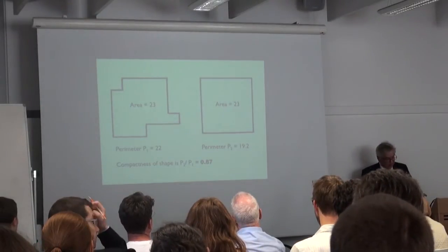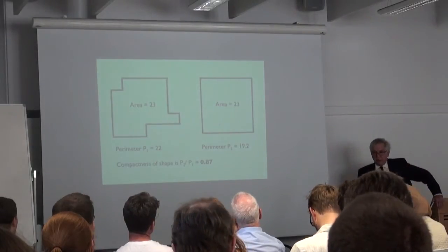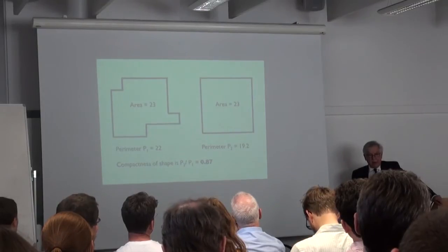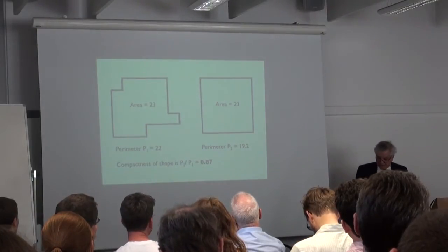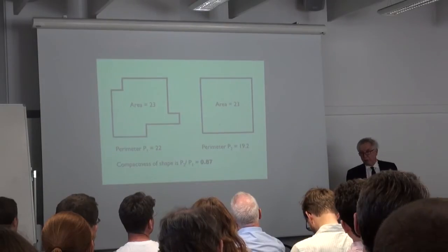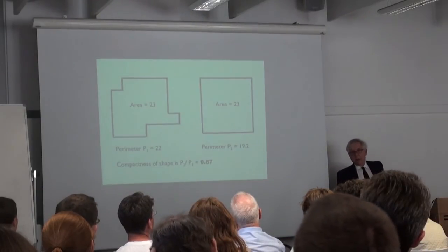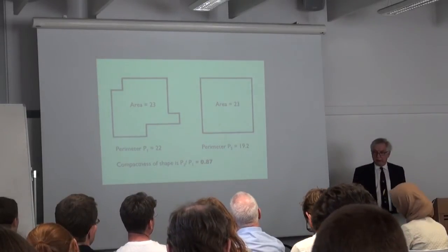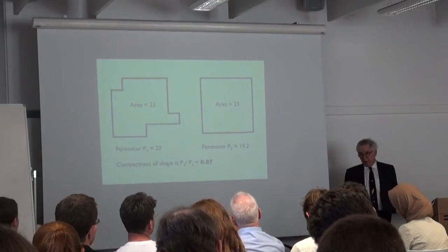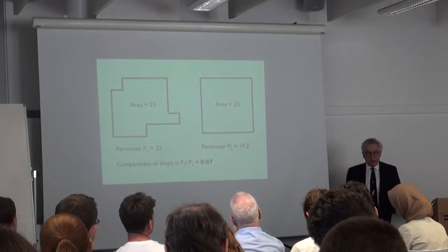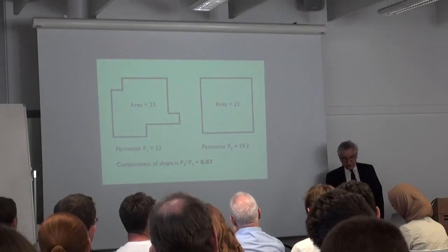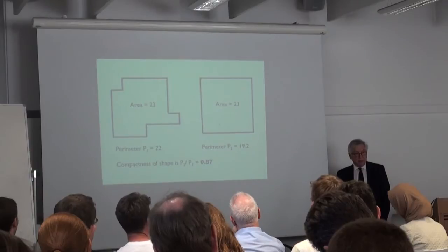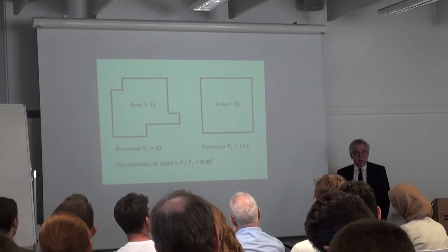The depths of buildings can have an indirect relationship to energy use, because there is a kind of de facto limit on plan depth, above which it's not really possible to light or ventilate the interior naturally, a kind of threshold of depth beyond which you must introduce air conditioning and permanent artificial lighting. Of course, there are plenty of buildings that can be naturally lit and ventilated that are not deep.